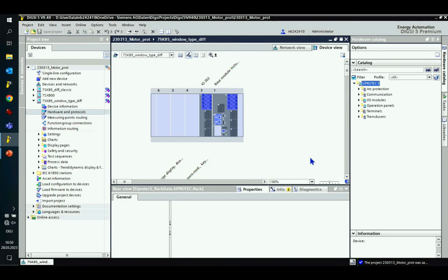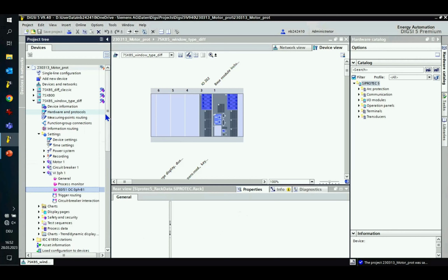Then you can have a look in the fault record and see what measurement errors are produced, how big the apparent differential current is, which in reality isn't there, and then put a good margin on top of that. So you come to values like 10, 20% of the nominal current. This should be fine here. Okay, so that's how to set this stage.